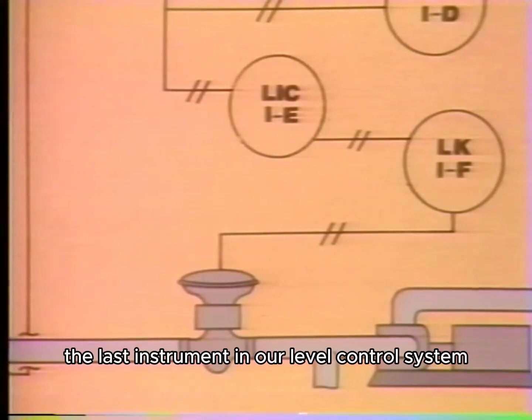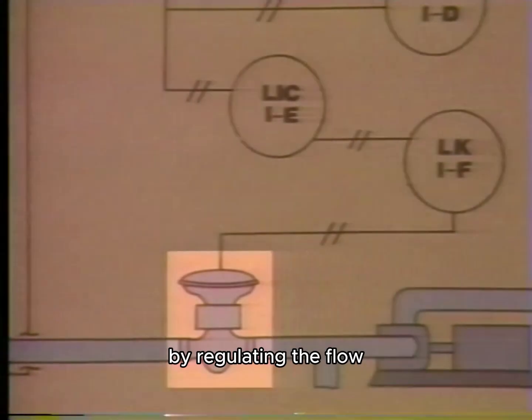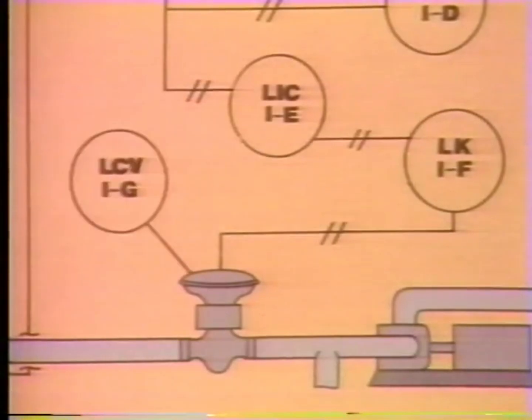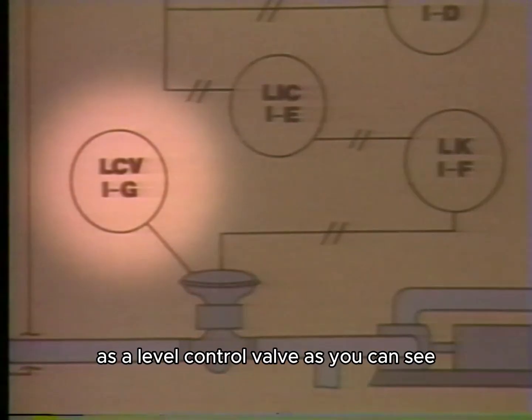So we now know that this symbol means this component is a level control station. The last instrument in our level control system, the final control element, is a valve that controls flow to the tank. By regulating the flow, the level in the tank is maintained at the proper level. In this system, the final control element is specifically referred to as a level control valve.